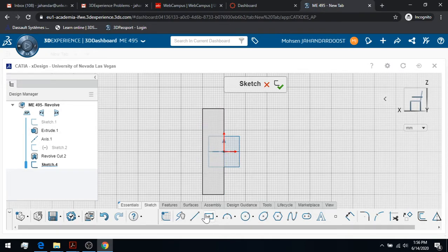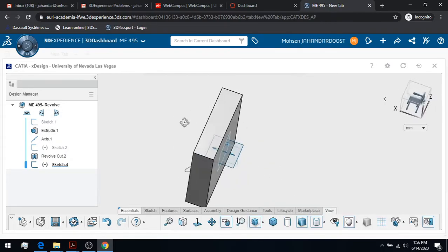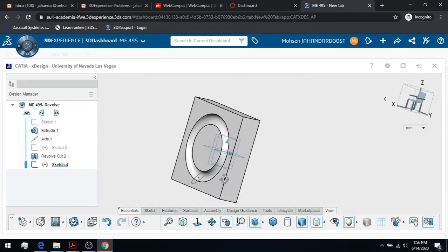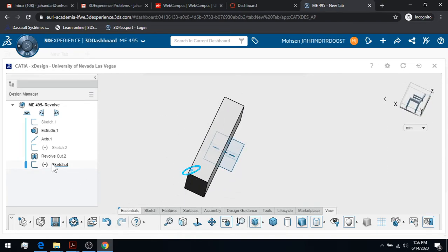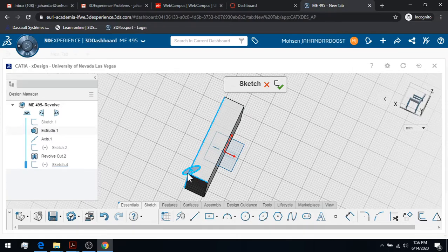profile. So now here let's try the ellipse. Let's see what we get here. So I select this type of profile. Okay, let's say that this is the profile that I want to cut through the base that I have. So I need to move it to the same face. I just want to cut it from the back, so let's delete this one.